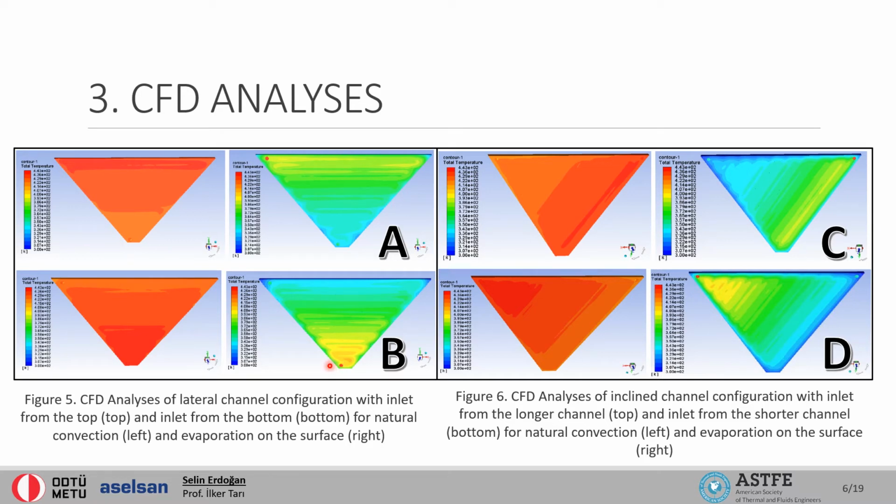The steady-state temperature for most of the vertical direction, this direction at the bottom, is higher than 100 degrees Celsius. The lower temperature regions are the ones that sprayed water might not even reach, these parts, because of the conical geometry.